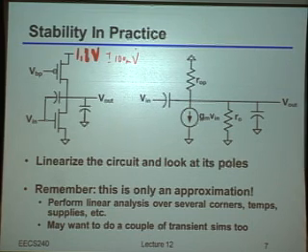Yeah, exactly. What happens when the thing is being turned on in the first place? Right? When it's being turned on, the supply voltage won't be whatever it's nominally spec'd to be. It's going to have to start from somewhere and make its way up. Typically it starts from ground and makes its way up. Well, what would happen if, for example, the circuit was unstable while the power supply was starting? If it's unstable, you may not be able to guarantee that it actually gets out of that unstable condition even once the power supply has settled to whatever it's supposed to be.